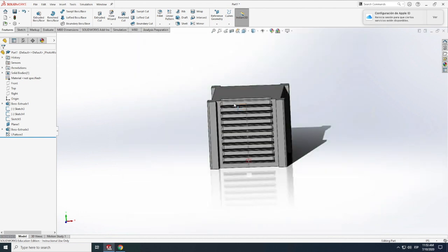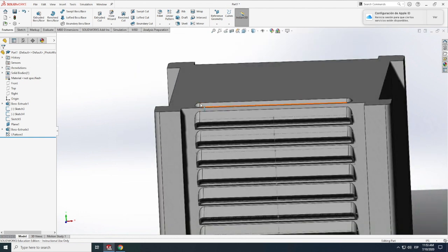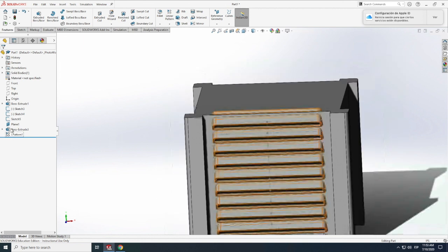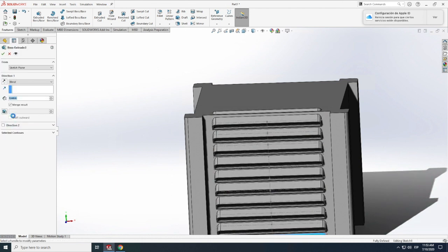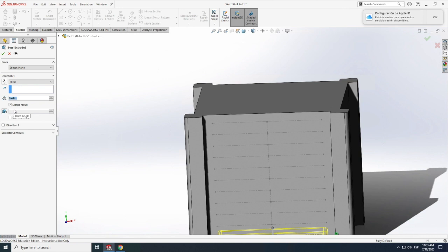Huh. What we might need to modify is a little bit, make that extrude be a little bit less. That way, so we'll go back here, edit, let's make the extrude be 0.25, that might be enough. All right, 0.3. There we go. Let's see.